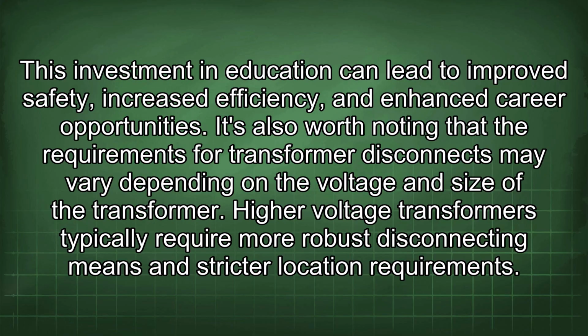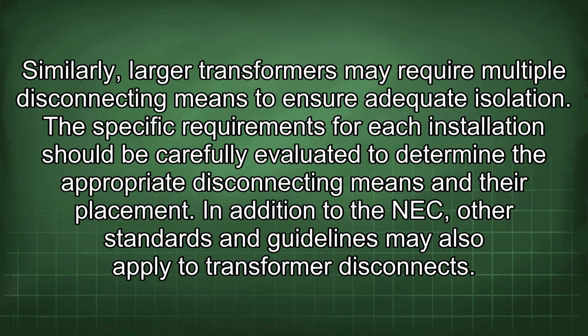It's also worth noting that the requirements for transformer disconnects may vary depending on the voltage and size of the transformer. Higher voltage transformers typically require more robust disconnecting means and stricter location requirements. Similarly, larger transformers may require multiple disconnecting means to ensure adequate isolation. The specific requirements for each installation should be carefully evaluated to determine the appropriate disconnecting means and their placement.